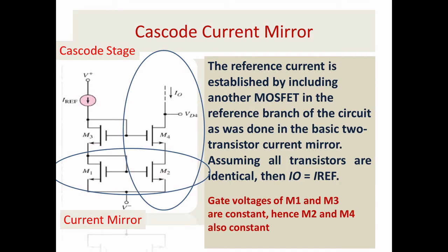So, very clear. See, this is your normal cascoded current mirror. First let me explain what is necessary here. This is the current mirror concept. M1 and M2 act as a current mirror, and M4, I said, is a cascoded stage. For M2, M4 is the cascode. Here another MOSFET is used: M3 is used to drive M4.